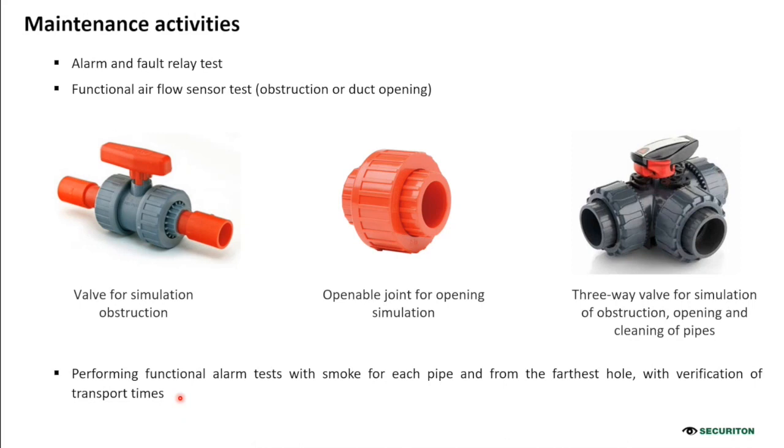Last but not least, you need to perform functional alarm tests with smoke for each pipe and from the farthest hole, with the verification of transport time. This test is fundamental, I have to say, because you check if the system performance is okay or not.